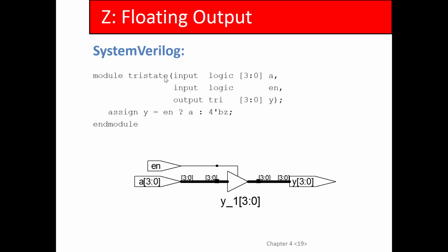For a free one, there's Icarus Verilog, and there's another one called Verilator. However, I just found out about an hour ago that Icarus Verilog doesn't understand SystemVerilog. It only understands pure Verilog, meaning that none of the examples in this book will work in Icarus Verilog, which really stinks. Verilator, I don't know yet. I was about to check that and I ran out of time. But I'll get back to you. I think Verilator might be a good option.